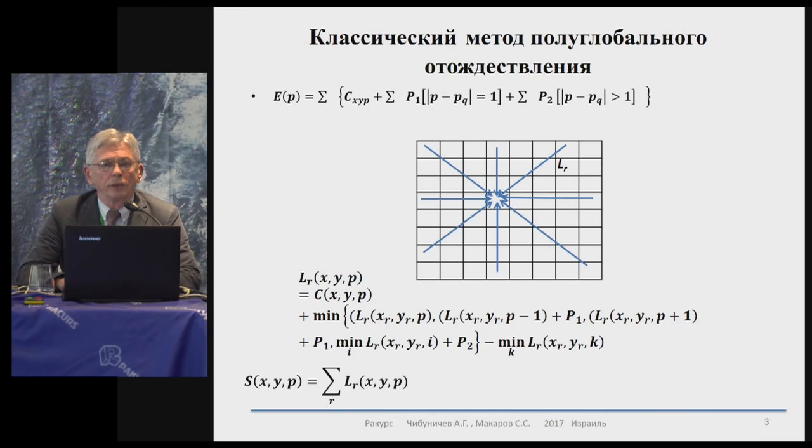It takes a while, and that's why they invented the semi-global matching method, which is based on the analysis of only pixels along one line. And there are 8 lines or directions usually. There could be more, of course, but people mostly use 8 directions, just like it is shown on this slide. As a result, we get the sum of all, yes, before I forget, and the bigger is the difference of lateral parallaxes with the neighboring pixels.